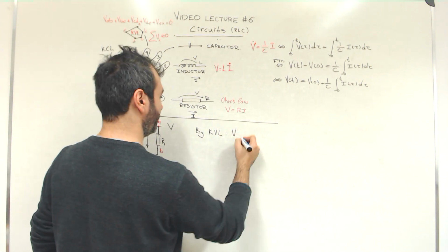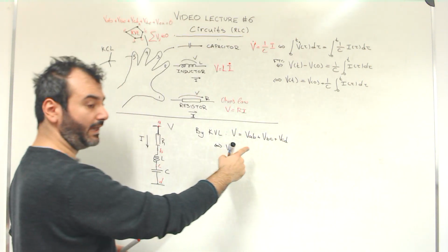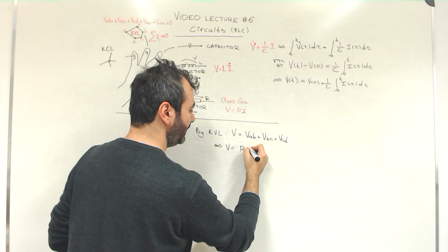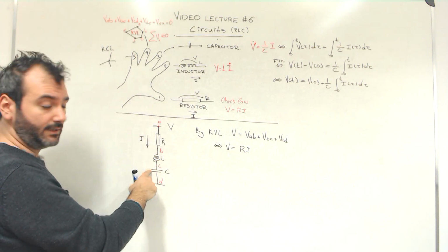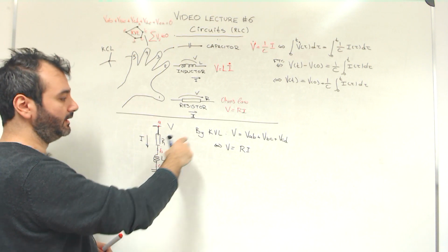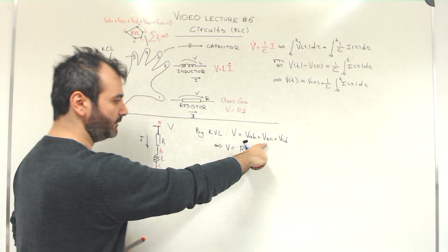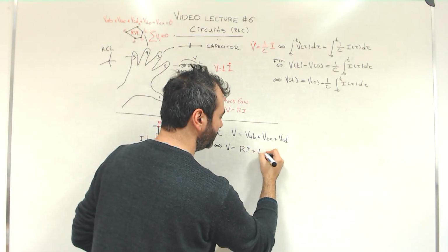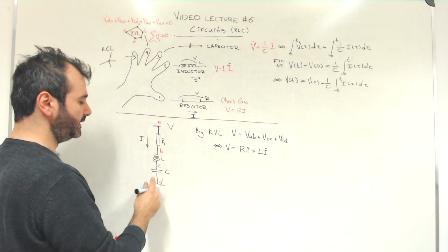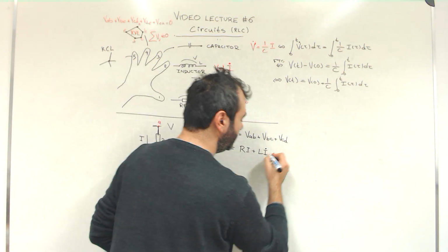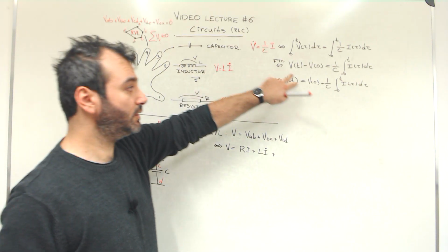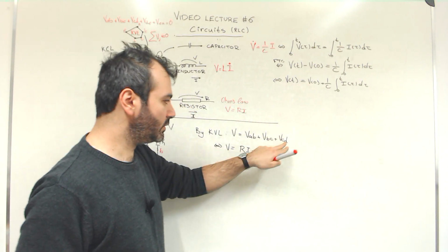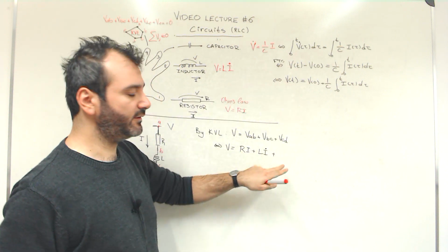This is our input variable, but I will simply keep the sketch simple. So we have VAB, the voltage across the resistor. From here we know that it is RI. From B to C, voltage BC is the voltage across an inductor. So we have Li dot. And for the capacitor, now what do we have here? It's either this equation or that equation, whatever is more convenient for every problem. We will take that because we're looking for VCD, not for its derivative.